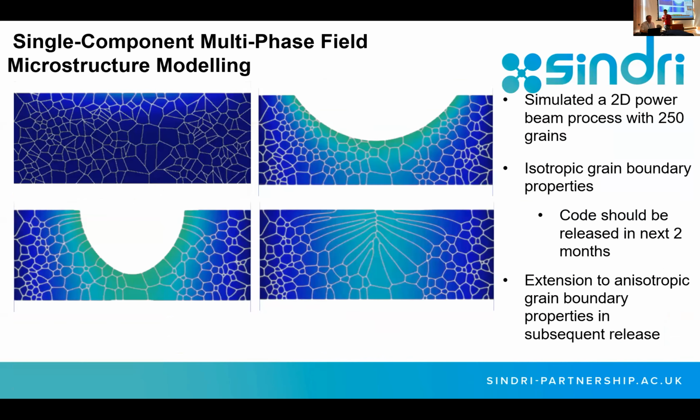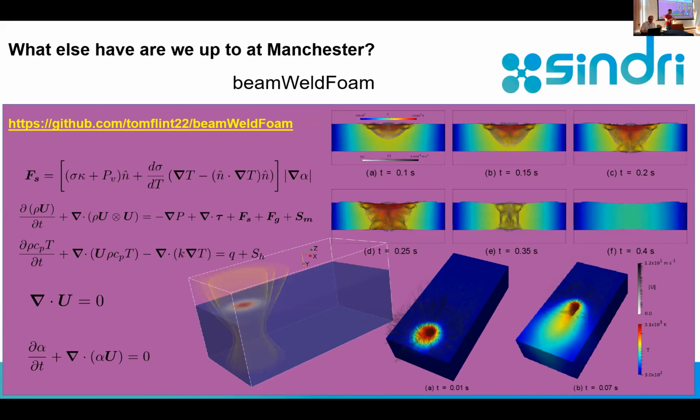And then on the next slide, this is applied to a welding type example. This is nominally an electron beam weld. There's gas on the top and the bottom, an initial microstructure, and the heat source applied. You get fluid motion, not shown here, Marangoni flow driving the currents, and it'll re-solidify. It works really well, and it's a lot more computationally tractable than the multi-phase field approach, which is very expensive.